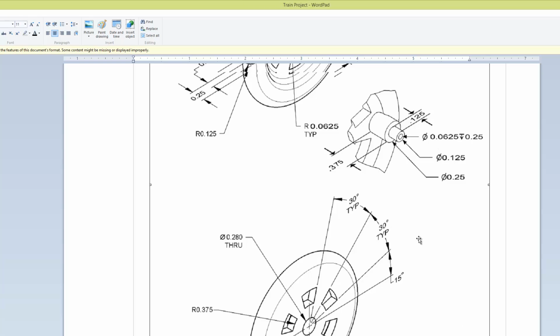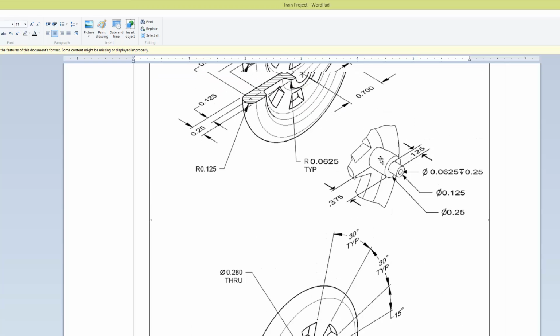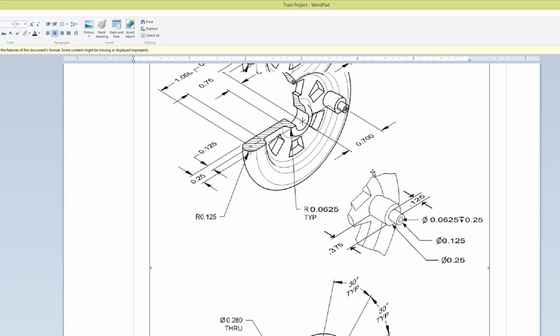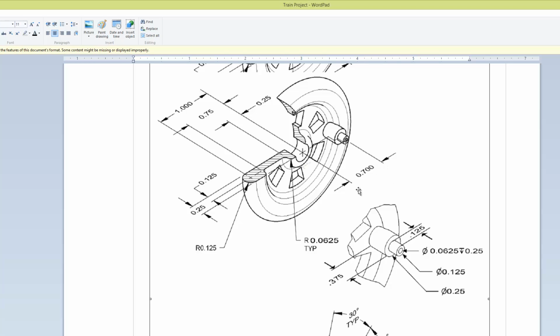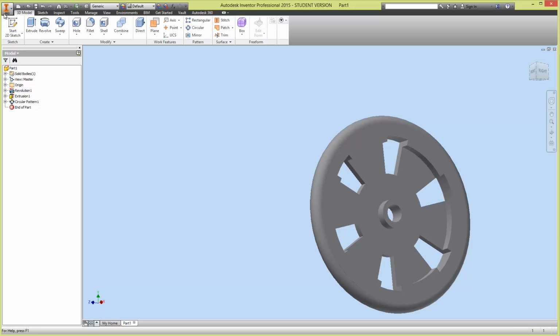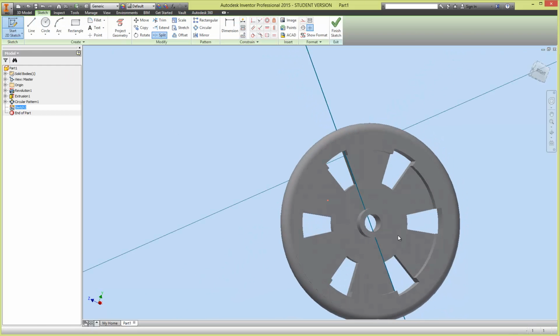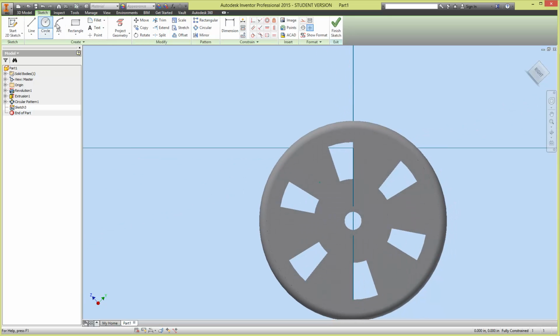Okay, lastly, we need to put this little linkage arm peg locker thing in here. It's essentially 3 circles. That is roughly 0.7 away from the center of the circle. So if I was going to make this, I would probably create a 2D sketch on this surface, and I would draw out 3 circles.